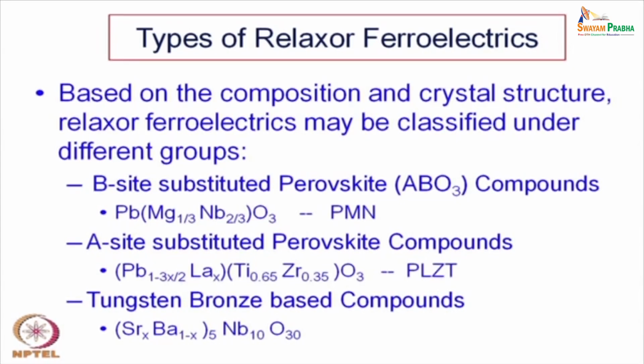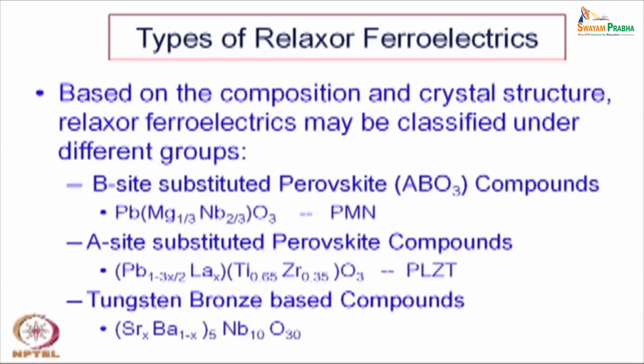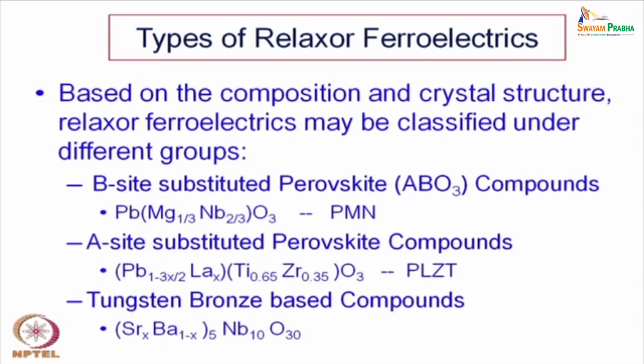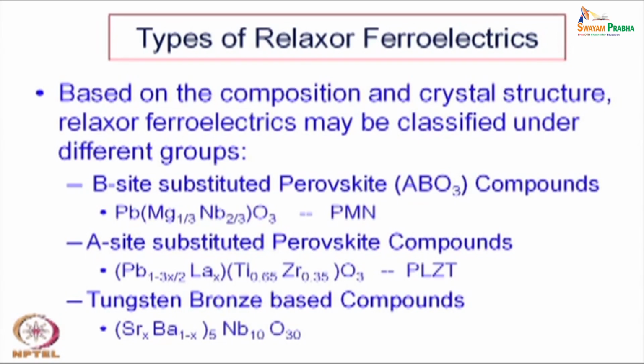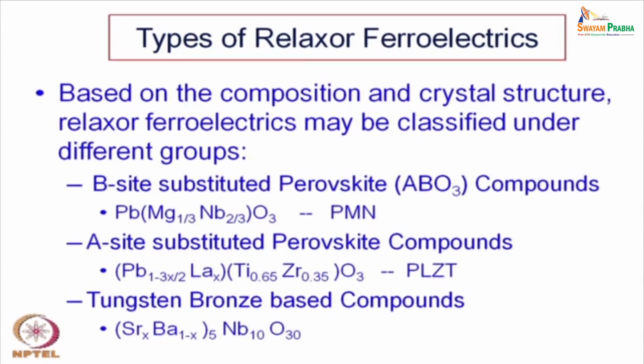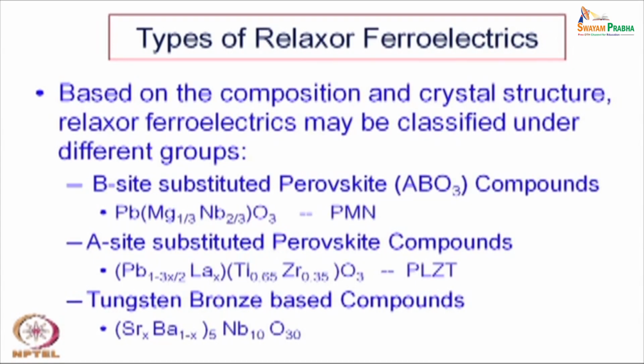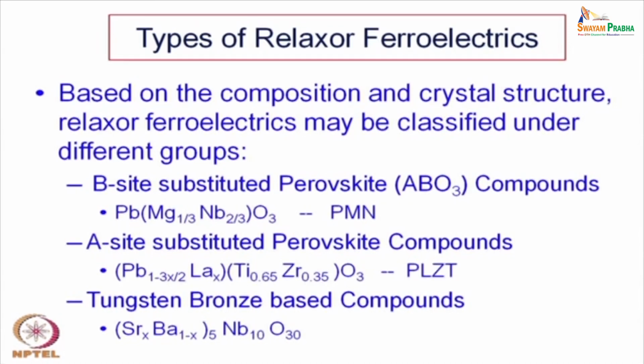The A-site substituted perovskite compound is PLZT, which is again a solid solution. We have discussed PZT in greater detail as a very important piezoelectric material, but here it is not pure PZT; lanthanum has been used as a substituent, as a dopant.